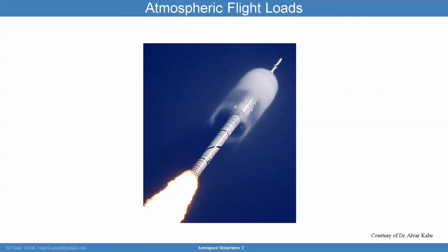And you could have parameters that vary, which could include the mass properties of the launch vehicle, the tank pressure, and vehicle configuration. As a minimum, the transonic and maximum dynamic pressure times of flight need to be considered. It is not unusual to interpolate launch vehicle loads from, say, two sequential time points in flight, because you want to then obtain intermediate points in flight. You have to be careful how you do that.